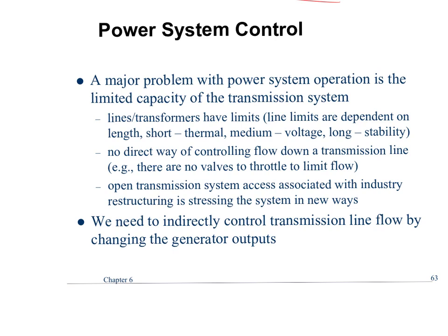Again, I think we talked mainly about this. We have thermal, voltage, and stability limits, and it depends on the line length is the bigger one. You can't directly control AC flow. You indirectly do it, right? So you bump up a voltage, you change a phase angle. That's why we have phase shifting transformers. Why do you think we call them phase shifting transformers? It changes power, right? Phase shift means changing power. So those big fancy phase shifting transformers, their whole purpose in life is to change the phase to move more power.